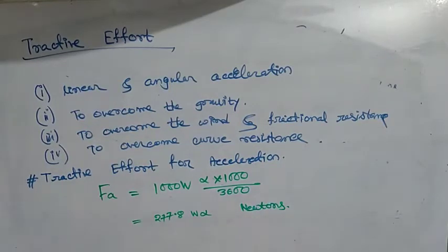Now when the speed of the train is being changed, it behaves as a mass greater than its dead weight, and this is due to angular speed variation of its rotating parts. Now if linear acceleration is f meter per second square and angular acceleration of rotating parts having radius of gyration r meters will be f by r radians per second square.